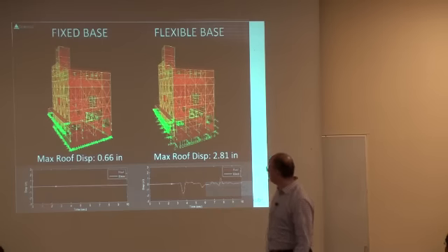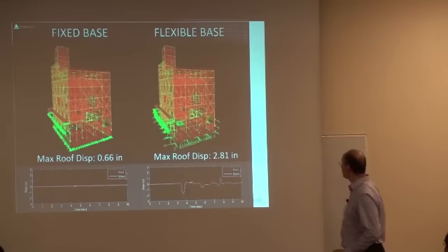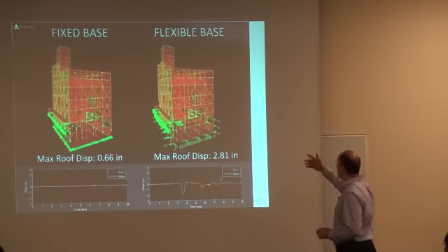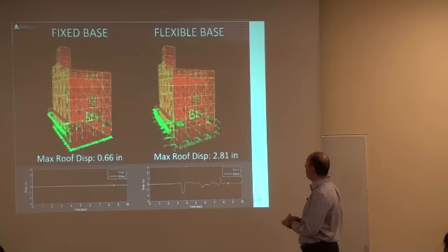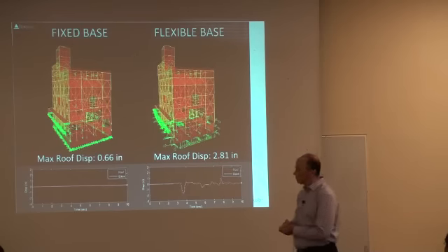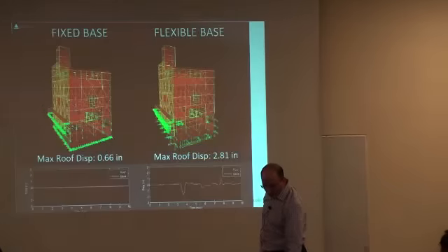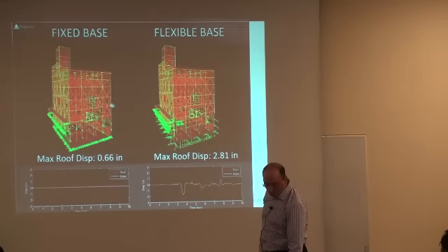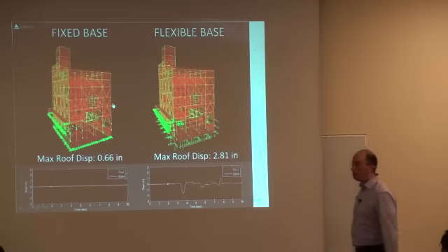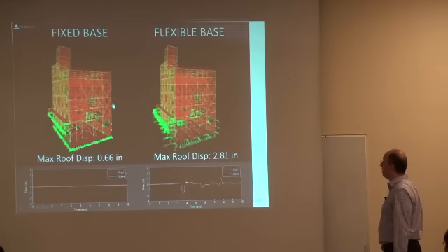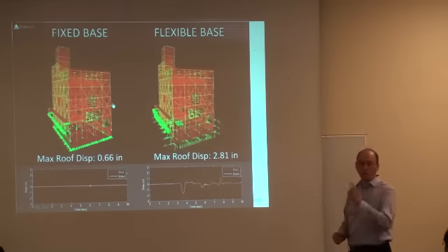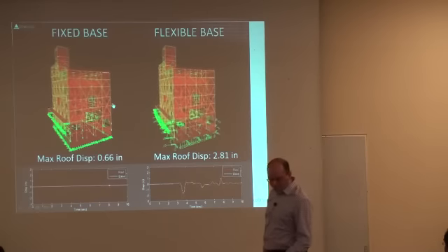That's a comparison of this building model. And on the right, obviously, you have soil structure interaction included. This is a very stiff building. So in a sense, including soil structure interaction for this building is, I'm going to play it again, similar to having base isolation. Your displacements may be a little larger, but it's going to reduce accelerations and reduce demand in general in your building.